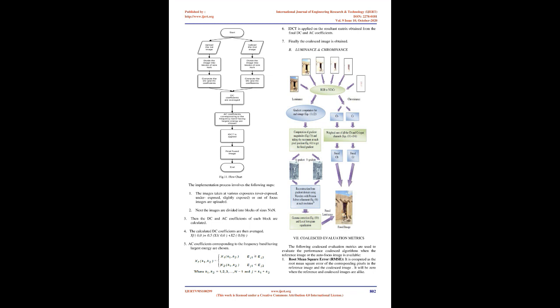Wavelet transform. An alternative to fusion using pyramid-based multi-resolution representations is fusion in the wavelet transform domain. The wavelet transform decomposes the image into low-high, high-low, and high-high spatial frequency bands at different scales, and the low-low band at the coarsest scale. The LL band contains the average image information, whereas the other bands contain directional information due to spatial orientation. Higher absolute values of wavelet coefficients in the high bands correspond to salient features such as edges or lines. With these premises, Lee et al. propose a selection-based rule to perform image fusion in the wavelet transform domain. Since larger absolute transform coefficients correspond to sharper brightness changes, a good integration rule is to select, at every point in the transform domain, the coefficients whose absolute values are higher. This idea is represented in Figure 7.